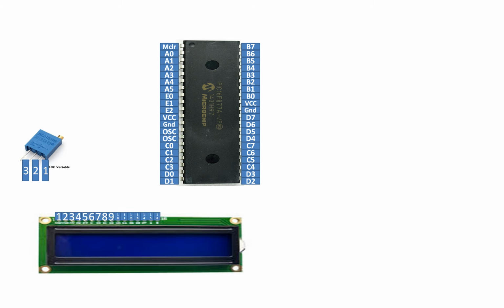Now guys, for the LCD, if you hold it like this from left to right, it is like 1 to 16. Now pin number 1 and 5 of the LCD, you common them, then you common it with the pin number 1 of your potentiometer, then you send it to the common ground like this. Then guys, for the pin number 3 of the LCD, that is the adjustable contrast pin, connect it to the pin number 2 of the potentiometer like this.